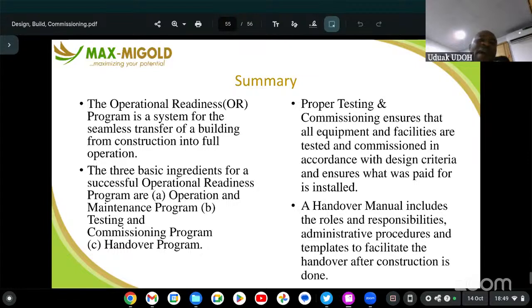We talked about the difference between testing and commissioning. Test is all about checking for functionality, guys. Check for functionality, check for errors. Are there any issues with this particular installed system? Now everything's working fine. But does it meet the required standard, what was planned, the end user's requirements and what was installed? And that's what commissioning is all about, and that's just different.